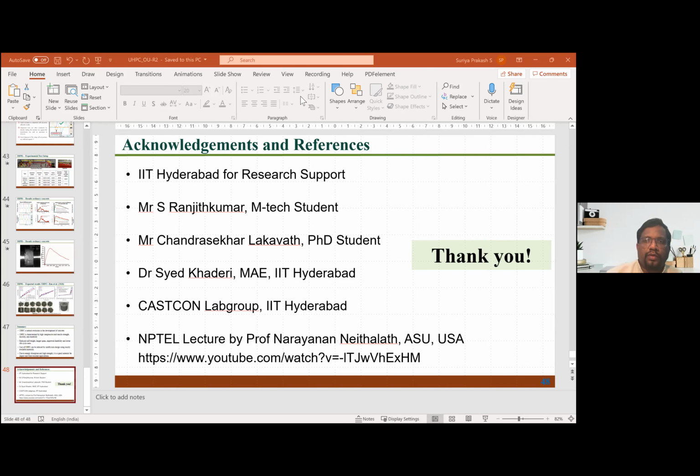Okay. Let me see. As the specimen is subjected to plastic deformations, how is the elastic modulus considered? No, we are getting the complete stress strain curve, right? So elastic modulus is only applicable in the elastic regime. Here, because I'm measuring from the wave propagation, the strain rate, and strain from integration of strain rate, I get strain over the entire duration, right? The stresses and strain. So I get the entire stress strain curve. So wherever you want, you can get your secant modulus.